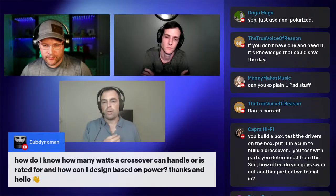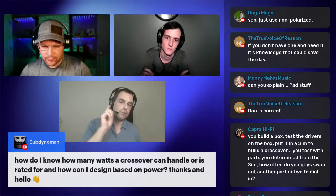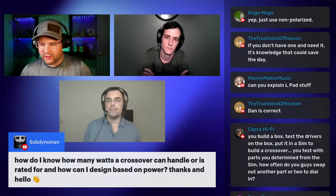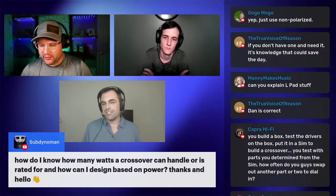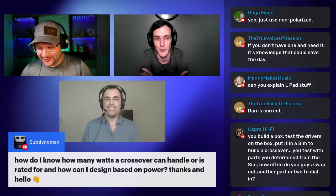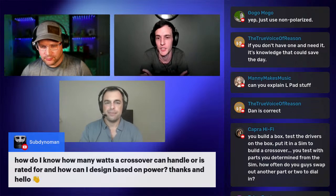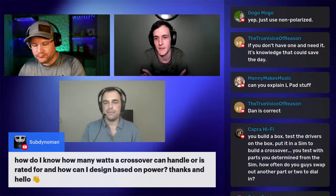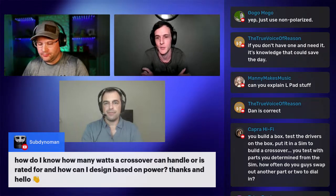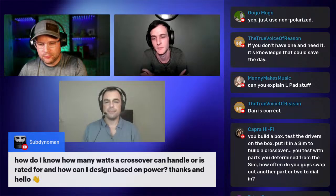If you're using 3 or more, it's 1 over R1 plus 1 over R2 plus 1 over R3 equals 1 over R. There's also just free calculators, which is better to use. I don't use those. I'm old school. Those are using the formulas themselves. Great point. They're all sharing the load that the tweeter is seeing, right? So you're spreading out the wattage over more resistors, so that it's not all heating up one single resistor.